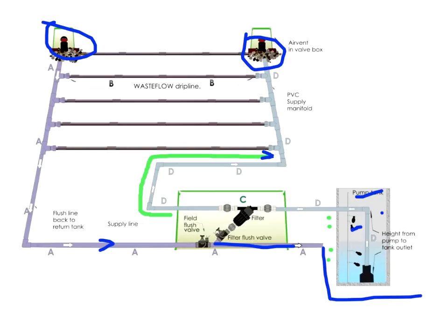We don't want to keep the pipe full. There are drippers that keep the pipe full, and I've known people to sell them for this sort of application. It's a very high risk keeping the pipe full. There are 2 reasons I don't like it, and 2 reasons it's dangerous. The first one, of course, if it's full and you've got freezing conditions, it will freeze.